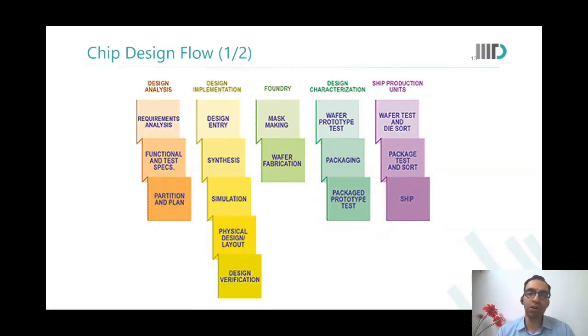So it would depend on technology and the choices that you have made regarding the design. The more the number of masks, the more the time it takes in the fabrication facility, because it has to sit in machines and run through them more times. Also, there is a higher risk of yield loss, because every additional mask step in the foundry means some yield loss at every step.